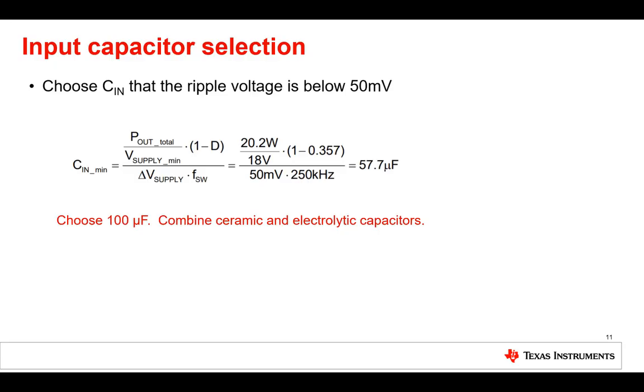Keep in mind that the input capacitor as well keeps the noise from the source. So when placing the capacitors, place the high-frequency, low-resistance ceramic caps close to the converter power stage. Then they will filter most. In addition, if space is available, spare footprints for capacitors might be helpful. For example, if the conducted noise during EMI measurements needs to be reduced.